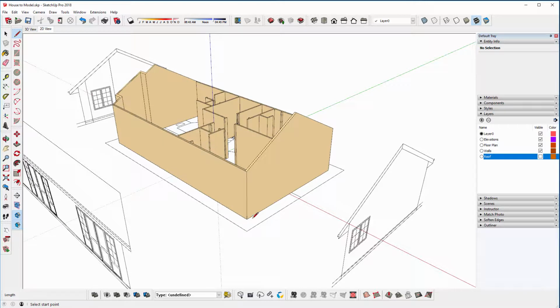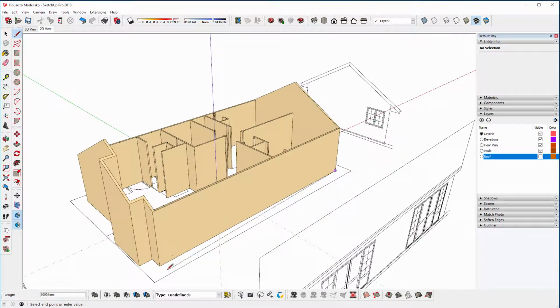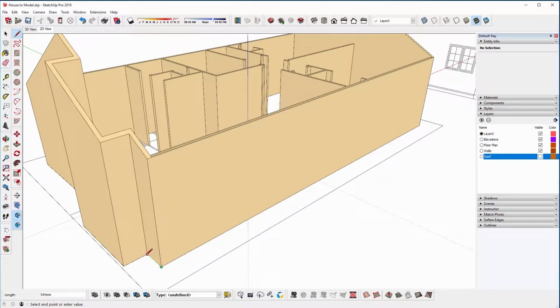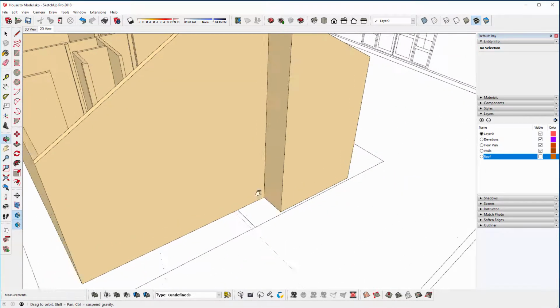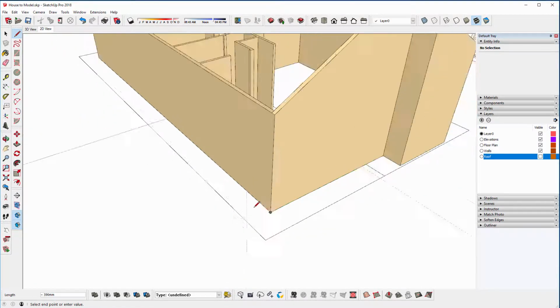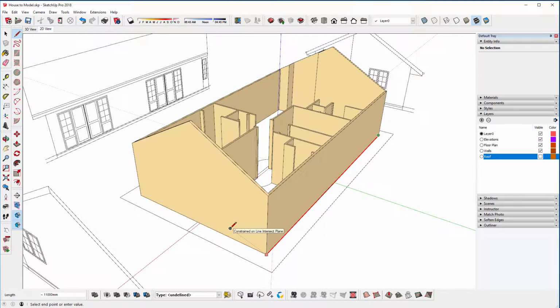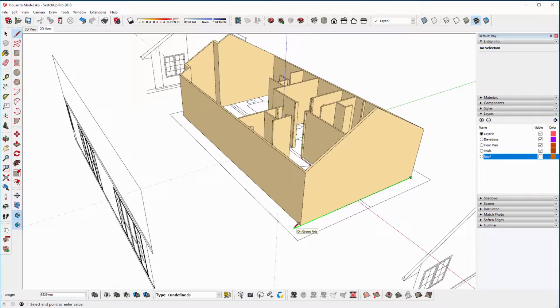So I can just trace around the bottom edge of the house, with the line tool, making sure you're on axis using the arrows or holding shift when you're on the right axis. And if you can't find endpoints, what I sometimes do is go past the line like that, holding shift or the right arrow, then touch the surface I want to intersect with. So click, go out past this way, hold shift, touch this wall or this face, click, and then it creates the face.